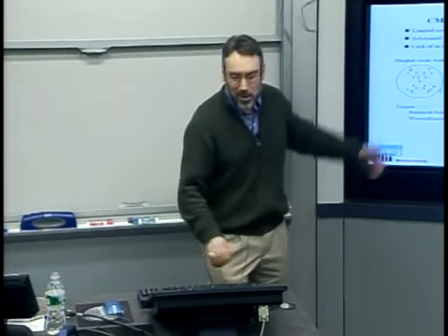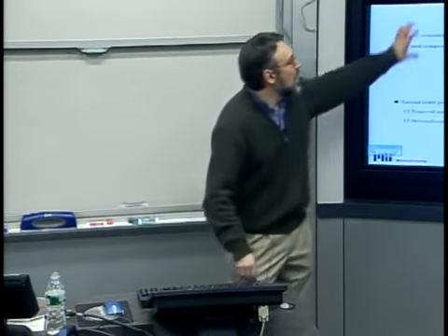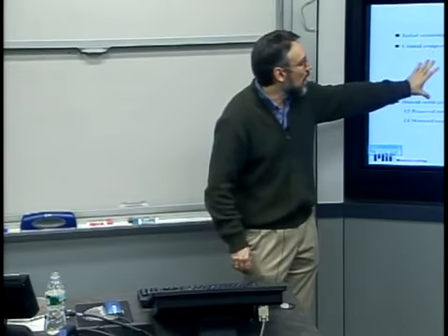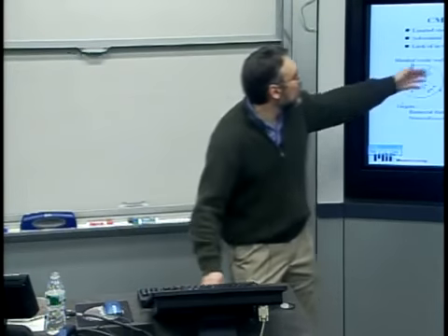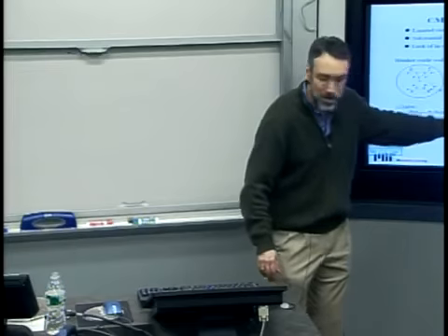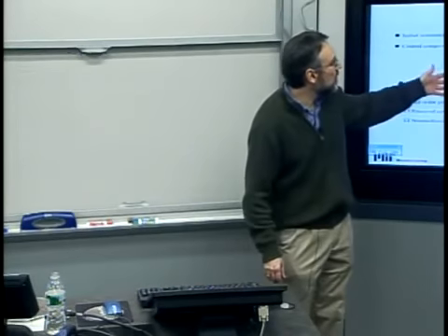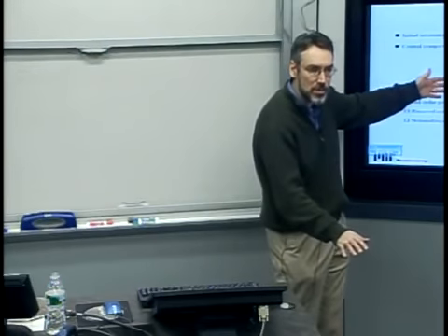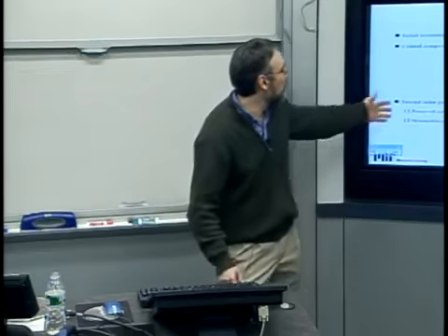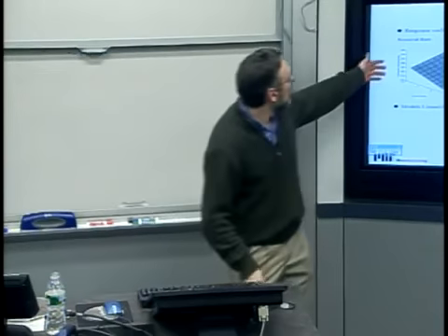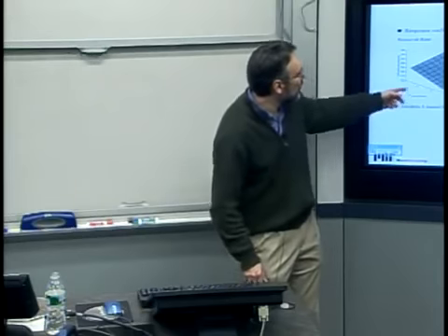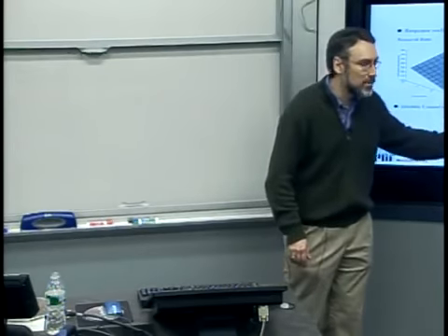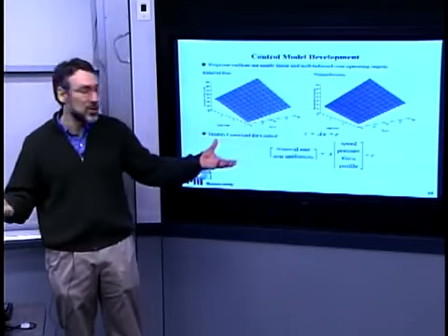And then the last thing I've already alluded to, but coming back to the CMP problem, we also can develop, and we'll talk about, response surface or empirical models that say, okay, here's what the removal rate is, or the non-uniformity is, as a function of some of the process conditions, like the speed of rotation, or the pressure or downforce. And once you have a basic control model, for example, the normalized removal rate is a function of downforce and speed, I've got some input-output empirical relationship between these.